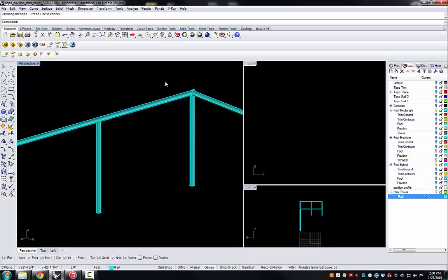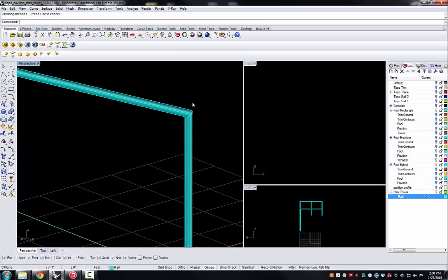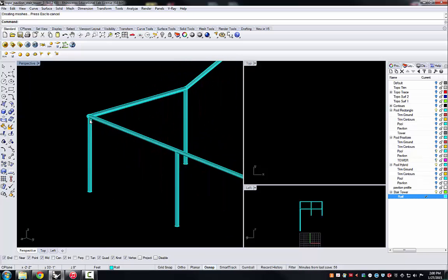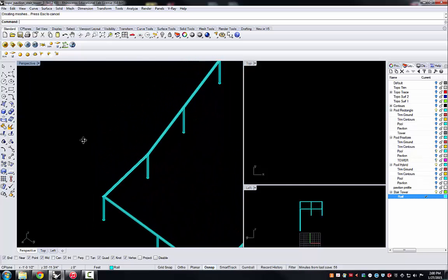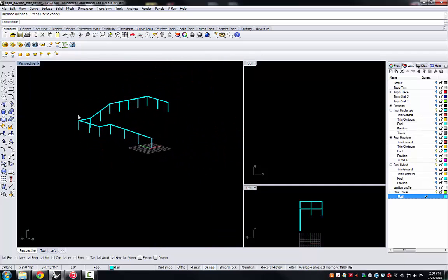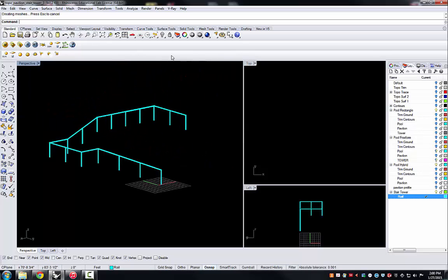And what you'll see is a series of pipes that create the handrails. They might look imperfect here. We could go in and put some radii into some of these corners to make them look a little smoother. But these will also render pretty cleanly when we make a final rendering of this. And so I'm going to accept all of that. I might select, in this case, all of the wireframe and hide that. So using a selection set, I'm going to select all curves. And I'm going to hide those.